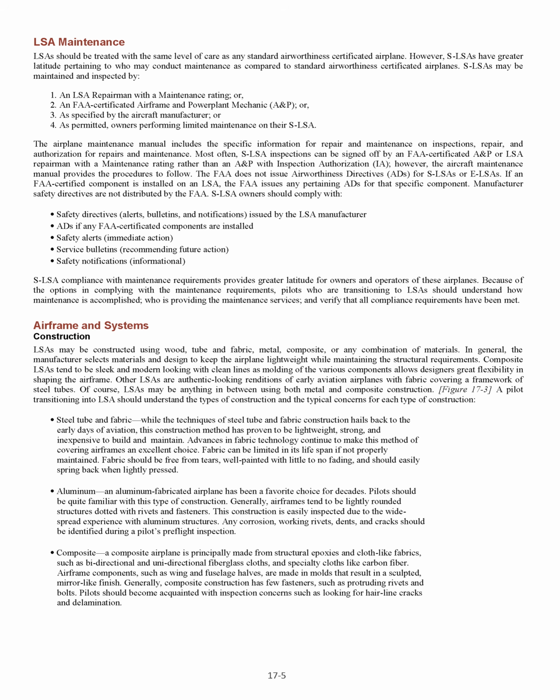LSA maintenance. LSAs should be treated with the same level of care as any standard airworthiness certificated airplane. However, LSAs have greater latitude pertaining to who may conduct maintenance as compared to standard airworthiness certificated airplanes. LSAs may be maintained and inspected by: 1. An LSA repairman with a maintenance rating, or 2. An FAA certificated airframe and powerplant mechanic, A&P, or 3. As specified by the aircraft manufacturer, or 4. As permitted, owners performing limited maintenance on their LSA.